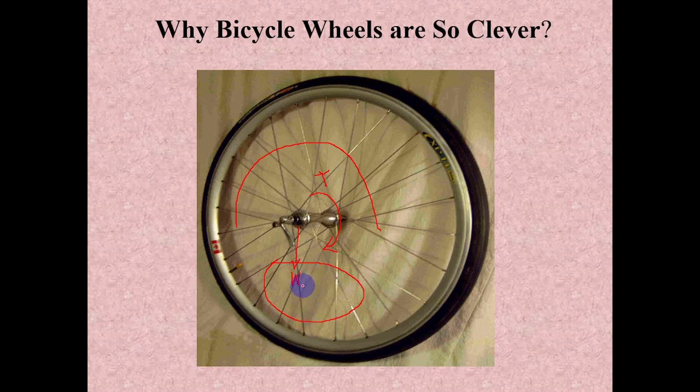For example, if all the spokes are subject to some 100 kg tension, due to this load W, these spokes will be reduced by, let's say, 20 kg, so from 100 it becomes 80 kg tension only. So it is working on the principle of pre-stress, which means it is going from high tension to low tension. It is not going into any compression.